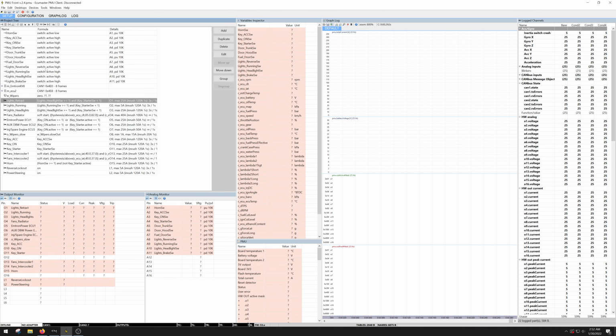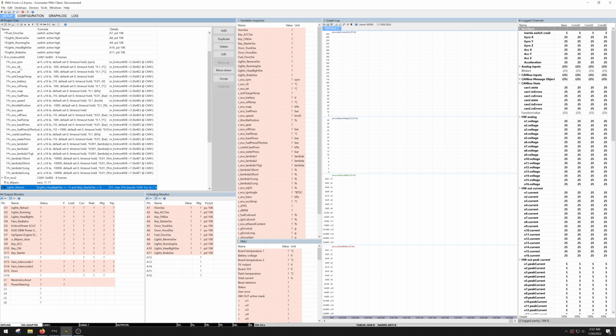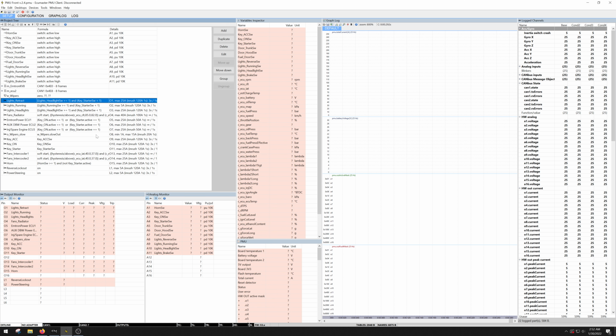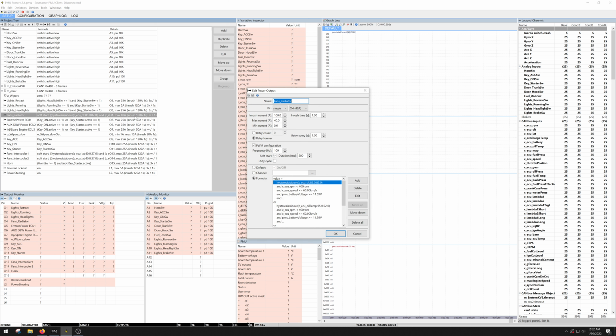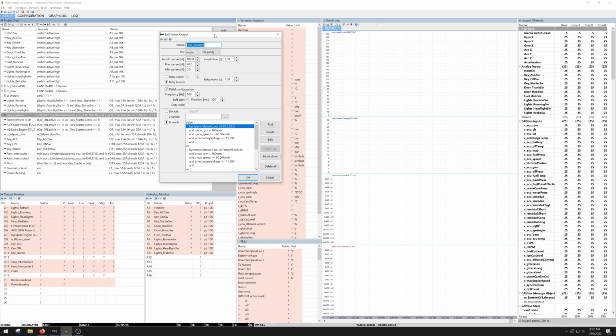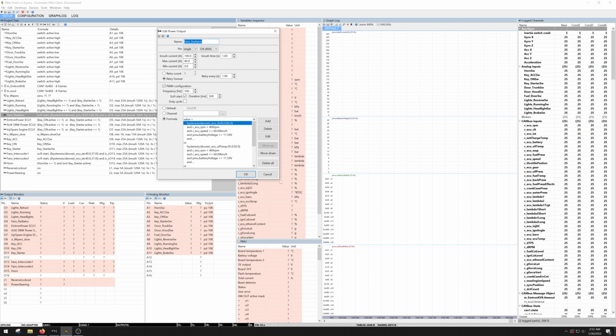So now going to the PMU, the current configuration that I set up is where this frame is coming in. It has like the default style. So when you're replacing engine RPM, coolant temp, air temp, charge temp, and I was setting all these up to make it so, let's say that I have a fan override. My fan starts off with, there's the display here for how I have it configured. There it is. So my fan, I have set as